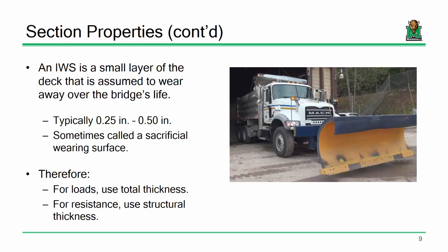The truck scraping the snow and the ice off the bridge, that tends to wear the concrete out over time. So what'll happen is we'll want to make a delineation between how much concrete we're actually considering for capacity and how much concrete was there when it was cast.